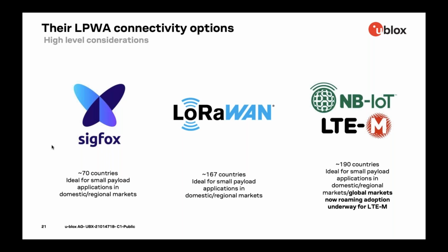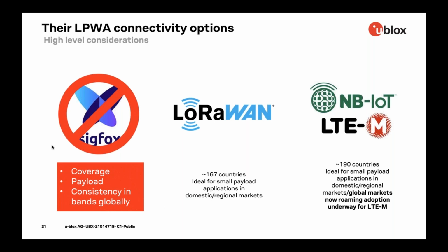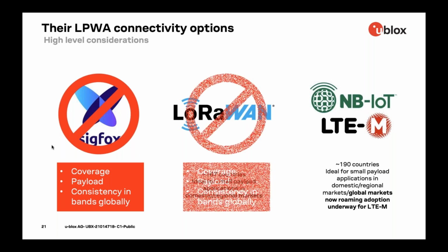For this particular use case, as one could imagine, Sigfox isn't necessarily the right fit. It has its place in the IoT market, but certainly isn't for this type of flexible tracking of cargo in trucks and products and what have you. And then LoRaWAN itself, even though there are a number of public LoRaWAN networks now available, often in parallel with a carrier themselves, there's the roaming capability, that these products could be sent anywhere in the world. Are the networks ubiquitous? Are they available everywhere? Do I need different radios inside depending on which region of the world they're working in? There are some challenges there with that type of application. They're obviously fantastic for other use cases, but for this particular one, it doesn't fit.